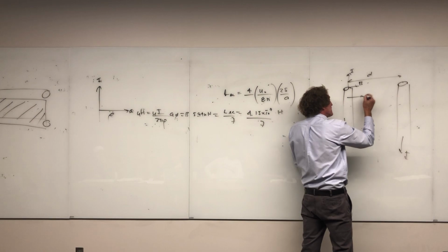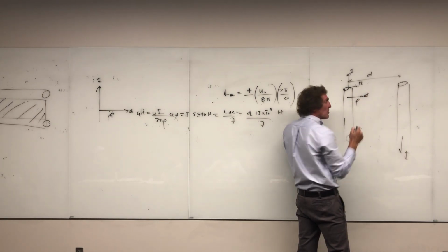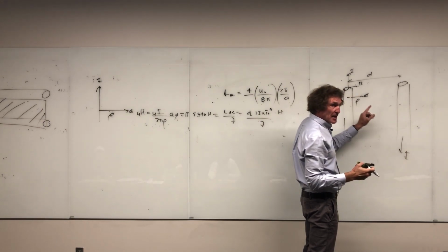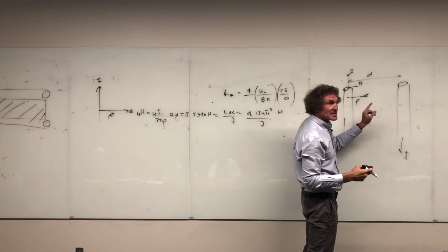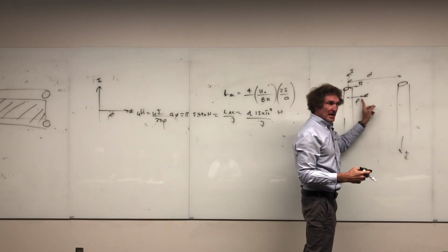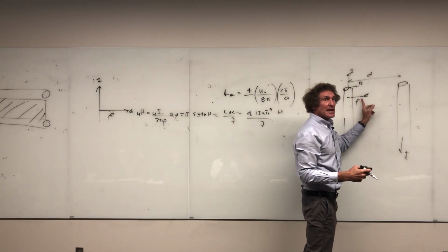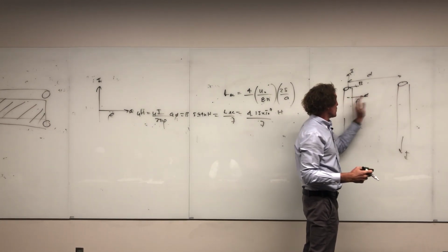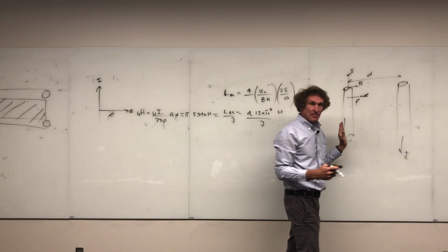Now I want the B field right here at a distance rho. The B field there is going to be the B field from this current, assumed infinite, by the way, plus the B field from this one at this point. They're additive. Then you integrate that B field over the entire region here, right?